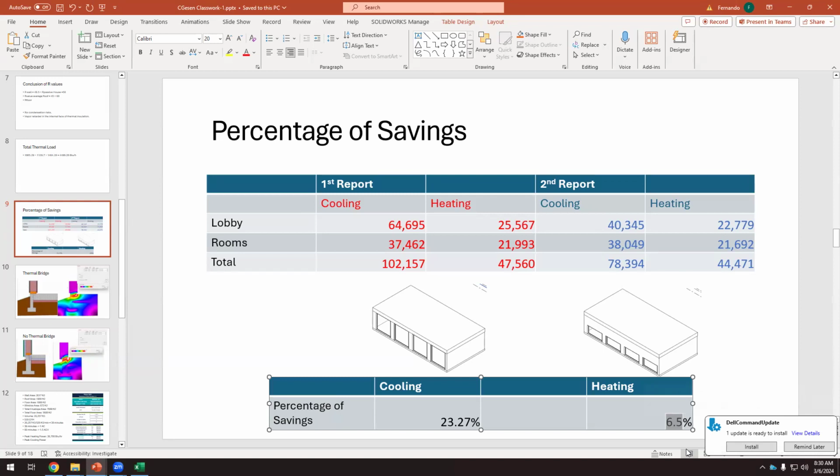So if I'm going to use the building mostly in winter, reducing the glass doesn't make sense. It makes sense because in this building, we applied most of the glass on the south side. If we had done this in the north, the savings in heating would be significant. But if we place most of the glass on the south side, the heating savings are not significant because